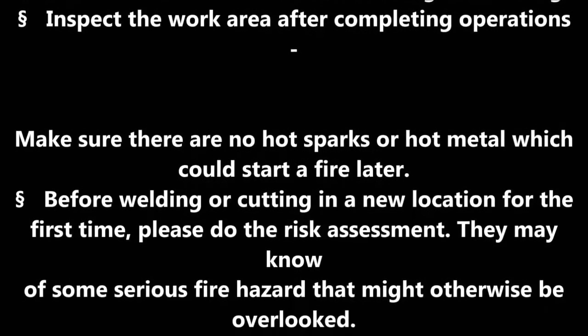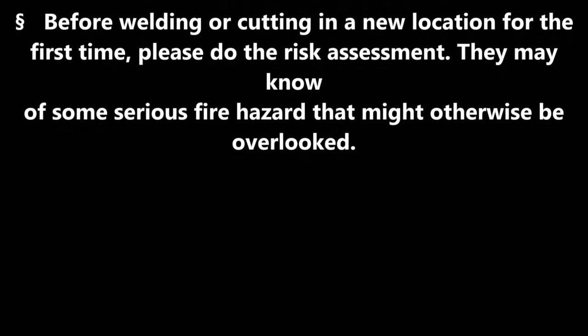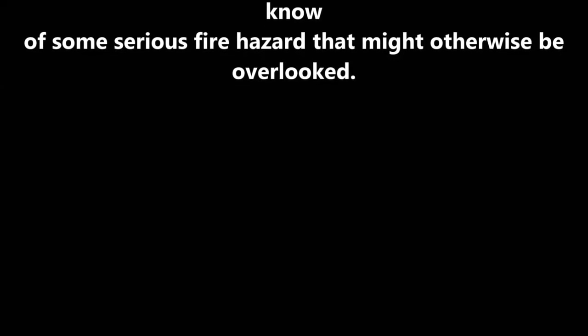Inspect the work area after completing operations. Make sure there are no hot sparks or hot metal which could start a fire later. Before welding or cutting in a new location for the first time, please do the risk assessment. They may know of some serious fire hazard that might otherwise be overlooked.